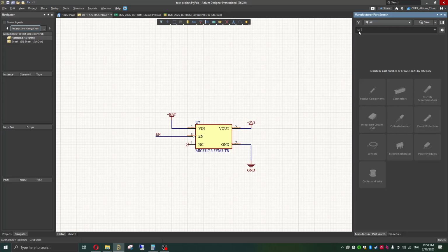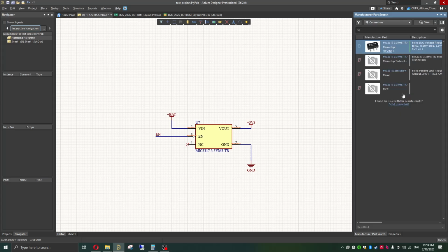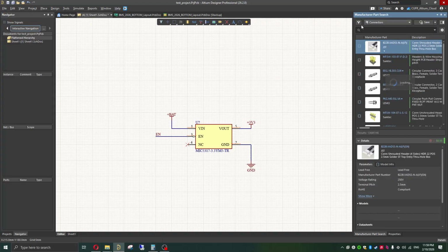Typically when you're choosing a connector, you want to consider the wire gauge, the ampacity of the signals, and the power that you're pushing. Also human design, you want to consider pitch between your connectors and also distance between your components and the connectors to make sure you can actually use this thing. But this is just for demo purposes, so I'm not really going to think about that right now, but heed my warnings.